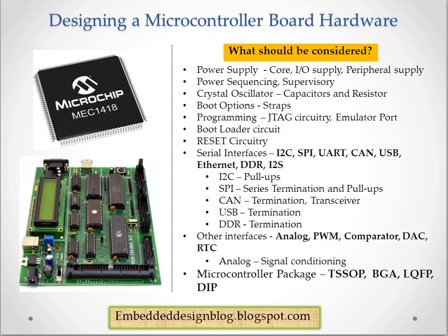So a specific reset circuitry should be built. And there is a specific requirement for the microcontroller power to be given at a specific ramp up time. The rise time should be controlled. So wherever you see a microcontroller design, there will be a simple RC used at the input of the power supply, which controls the ramp up of the voltage to the microcontroller.